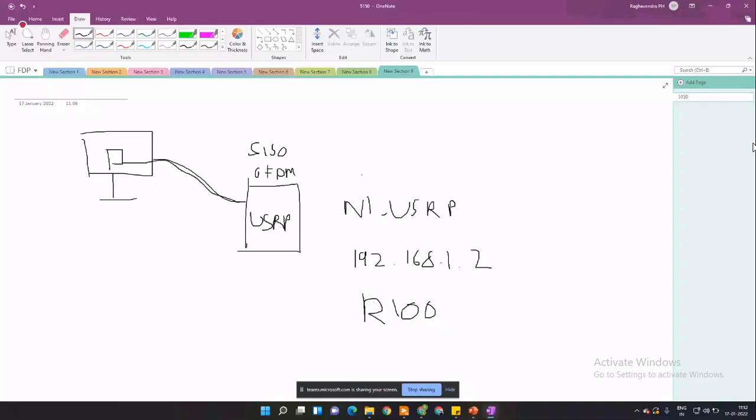So if I have another application, so let's say I have this particular USRP with me and I am using a particular LabVIEW code to run some code on this. If a second application tries to access this, the session will not be given to that application because something is already running this. So that is how we manage hardware on a software. We open something called a session, and at the end, we always close the session so that any other software that is trying to access this at a later point can do so. So opening a session and closing a session is actually an important concept.